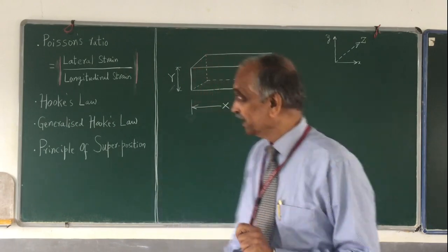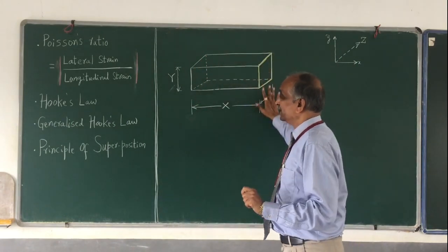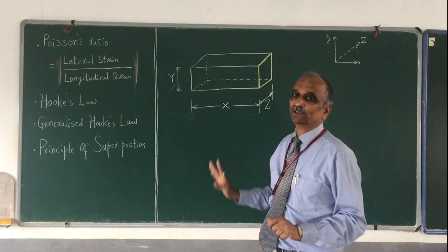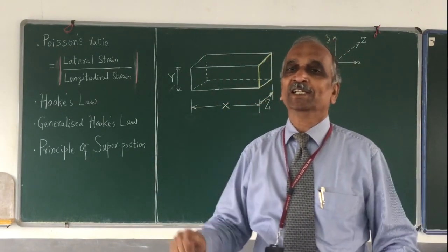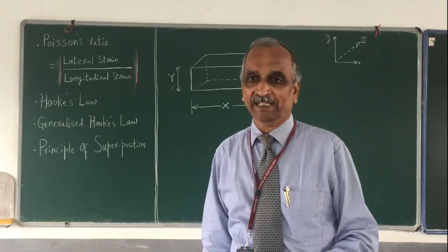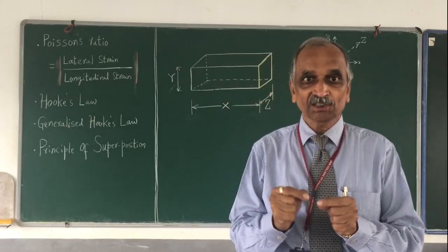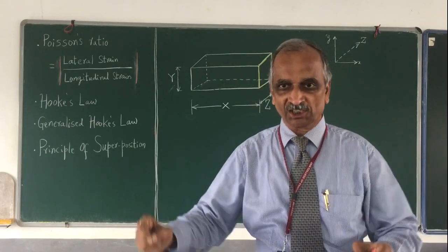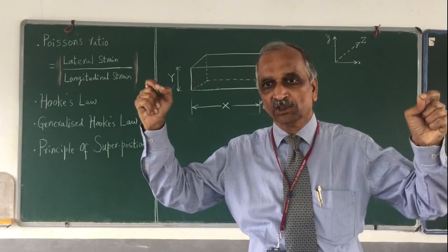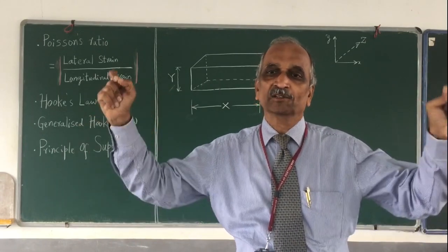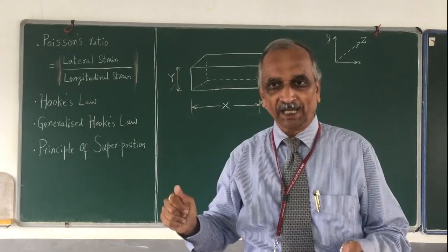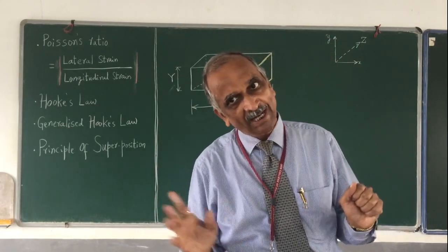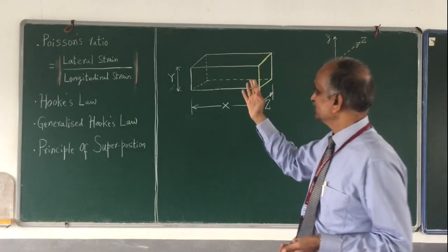Okay, so as it is, I am unable to say what the longitudinal direction is, because only once I apply load shall I know what the longitudinal direction is. Strain in the direction of the stress, or strain in the direction of the load, is what is called longitudinal strain. And any strain perpendicular to that is what is called lateral strain. Okay, I hope you understand.